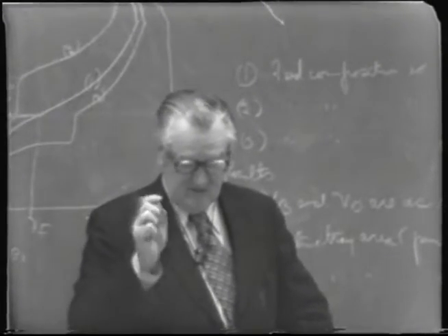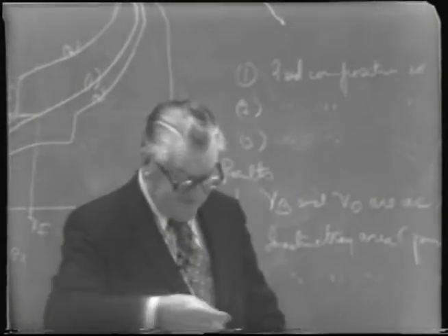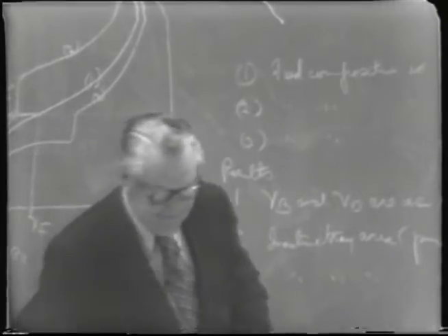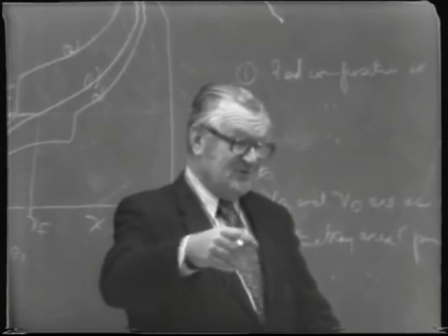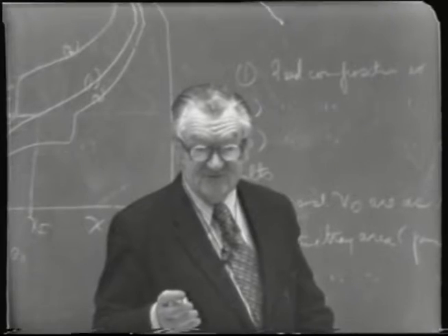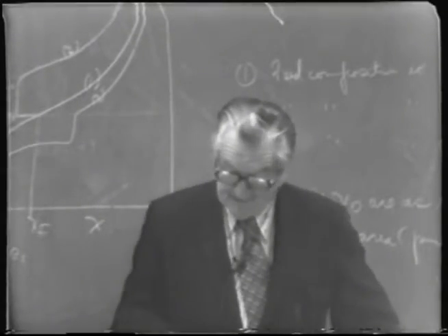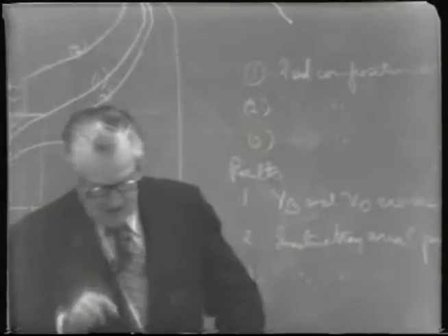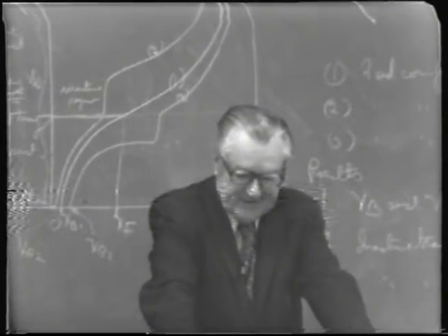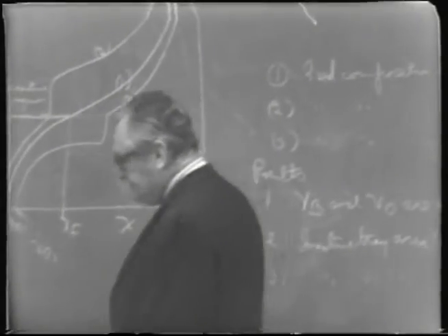Maybe next time I'll work out a little example there, but you could do it yourself. Assume a feed rate of 15,000 gallons per hour, like this problem we're going to work on here, and consider what it would be if you only had 2% alcohol instead of 7% alcohol for the same number of trays. Now, the question of plate spacing, in its simplest consideration, is very simple.